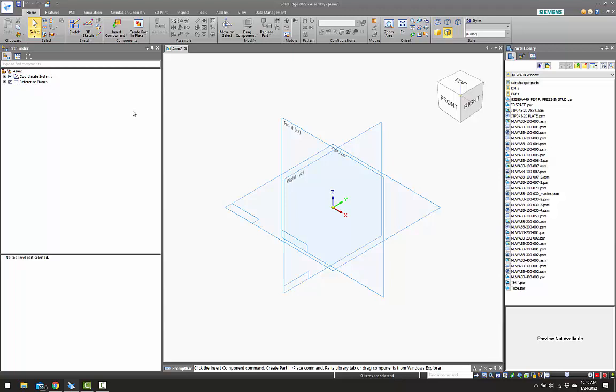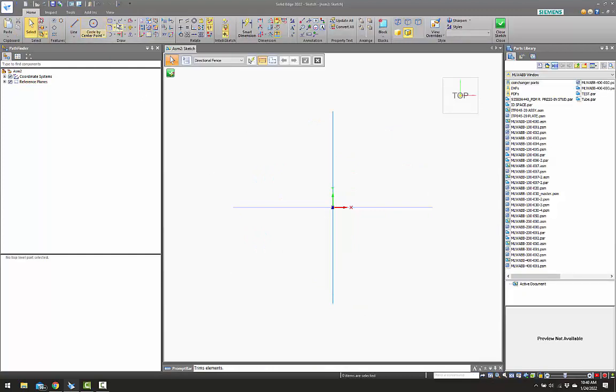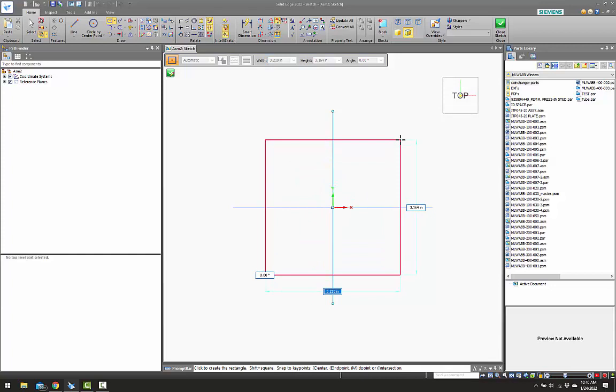Usually it'll pop up a little warning message that you need to have it saved. So what I want to do is design some sheet metal parts around a tube frame. So very quickly I will draw a sketch and start creating the stick frame for using frame parts here in the assembly.